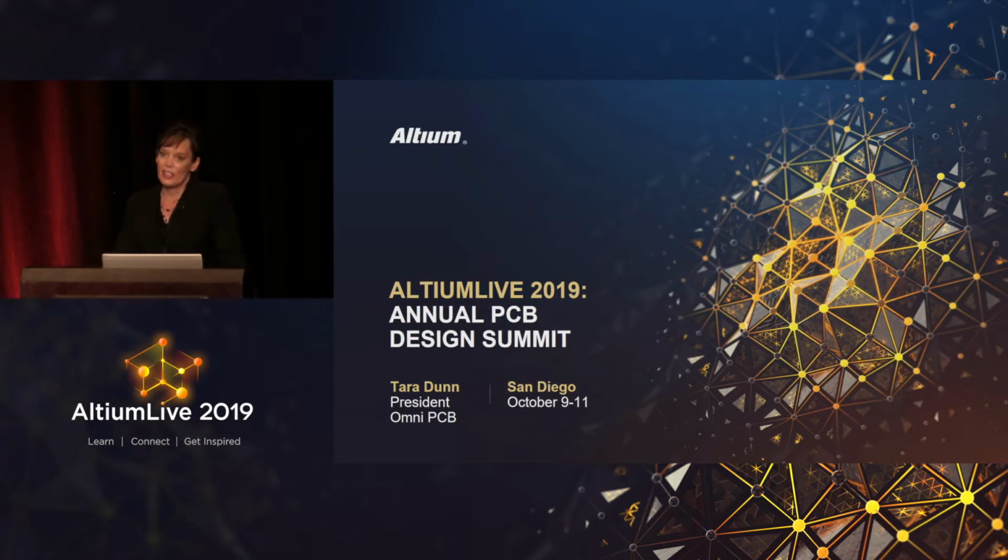So we changed materials. We started out with adhesive base. We switched to adhesive-less, so it would be a little bit thinner, give you a bigger bend radius. And then we cross-hatched the shield on the back side in the area that it's going to flex. Great, ran some prototypes, shipped them. A couple of weeks later, hey Tara, we still got a problem. This isn't working. I'm like, okay, do some more talking, some more brainstorming.